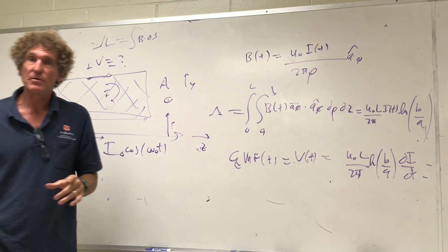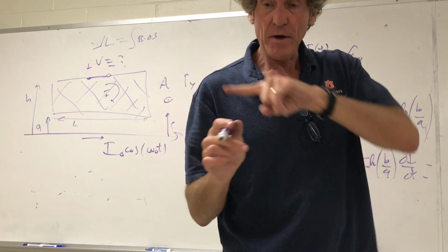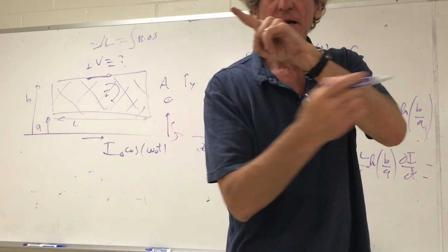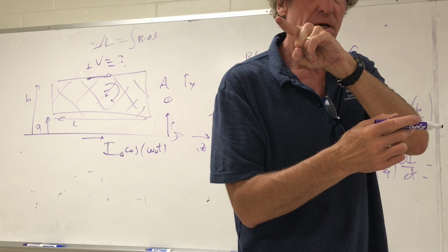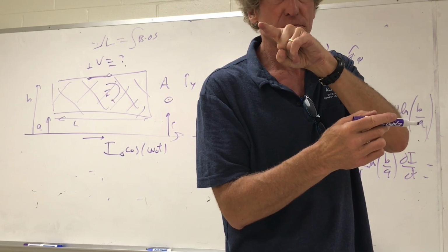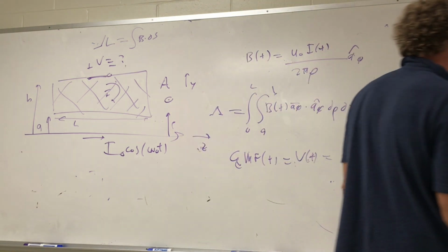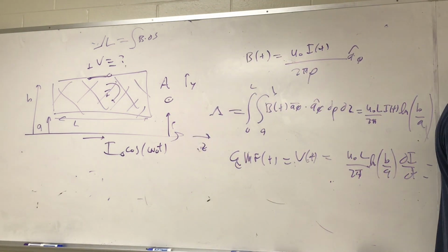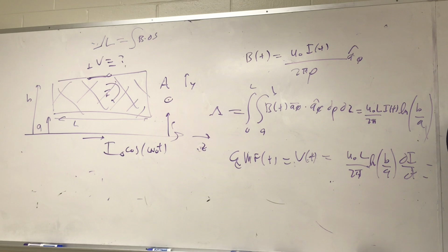Now here's the thing with grounds. This is where it applies. If you have a closed loop, and any kind of high currents near there, time-varying currents, you get an induced ground loop current that can be a real problem. So if you have a system, and this is something where we're going to talk about either signal to chassis or chassis to earth ground, it doesn't matter.